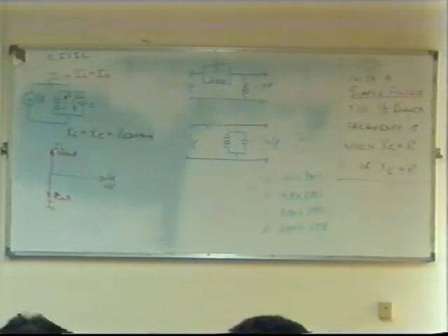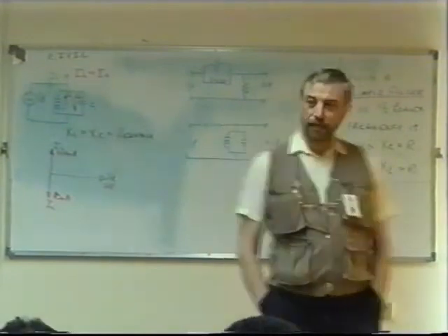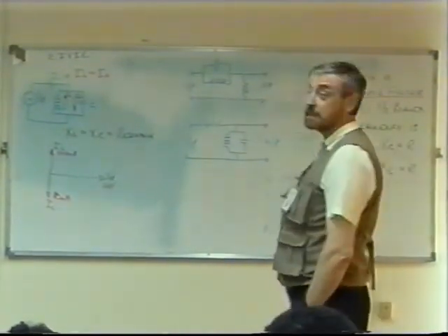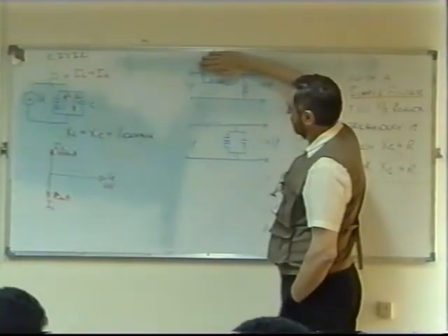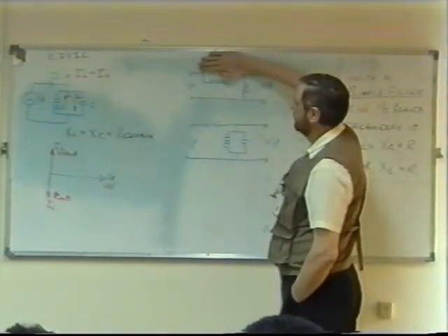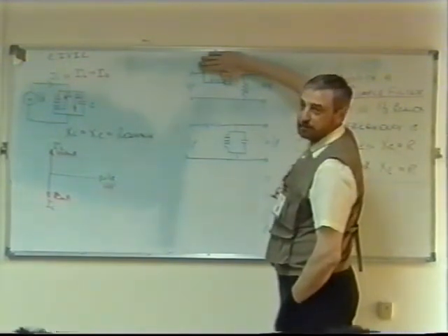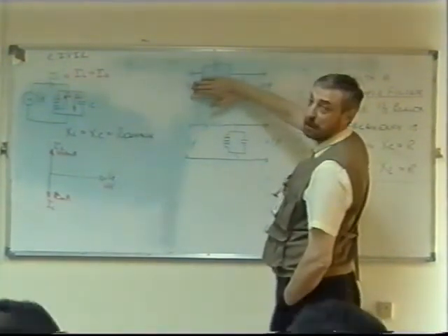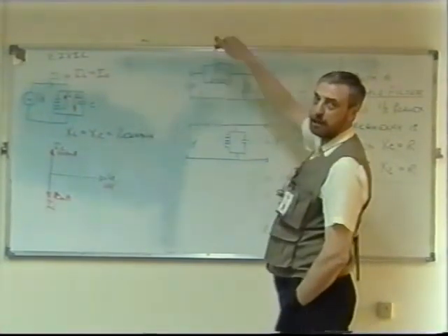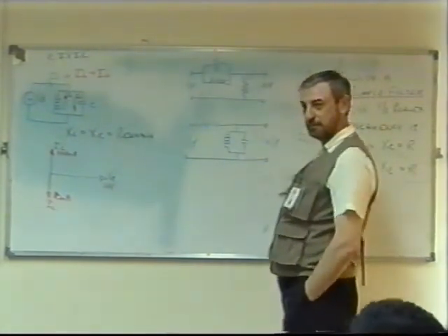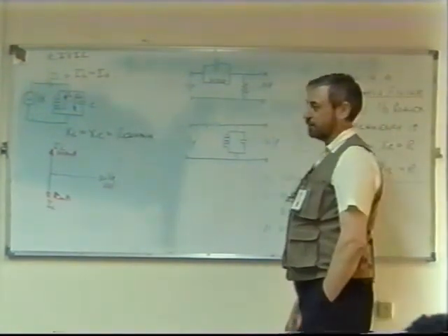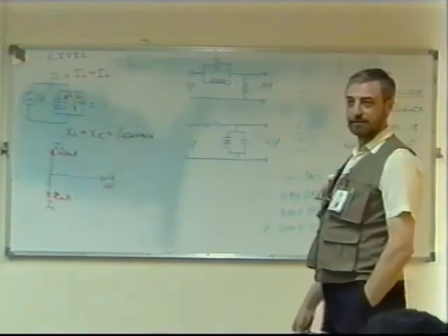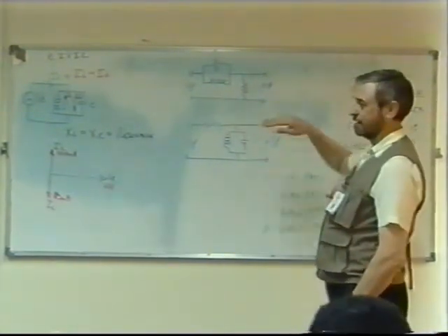Think about D. What is D? Band stop. If we think about high pass and low pass, in the examples I gave you before, if that was the circuit, it's a low pass filter. If that was the circuit, it's a high pass filter. Now we've got a high and a low, so it's either band pass or band stop.